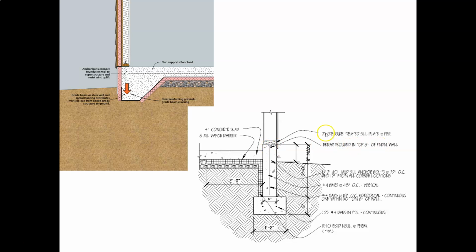And then there's rebar again, and a pressure treated sill, the first place where the wood meets the concrete, and then we have our concrete slab coming in. It's 4 inches deep, and below it we have our vapor barrier, and below the vapor barrier again we have the insulation, and then it looks like crushed stone down there as well. So a lot of information in there.